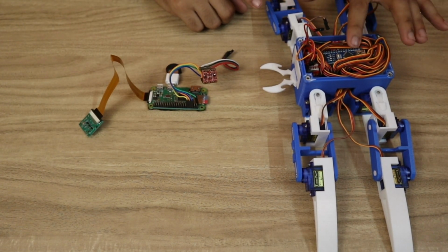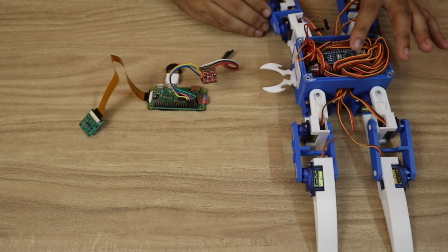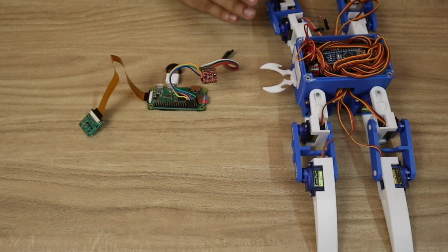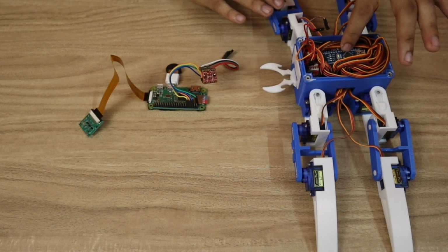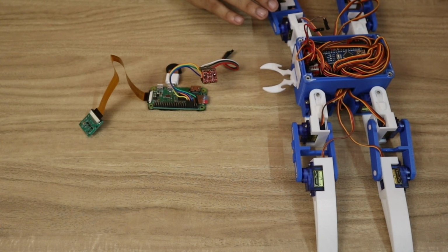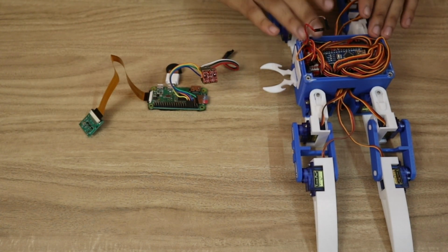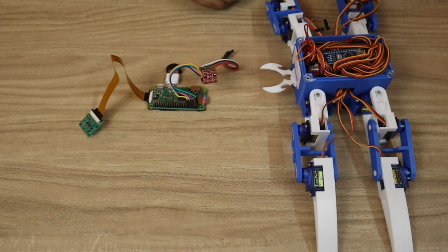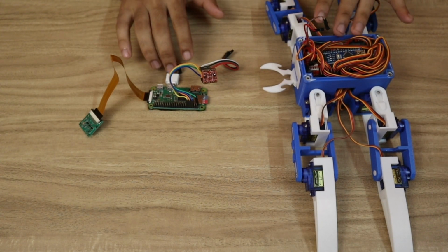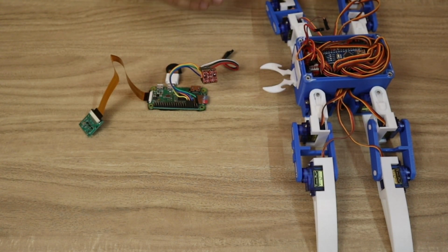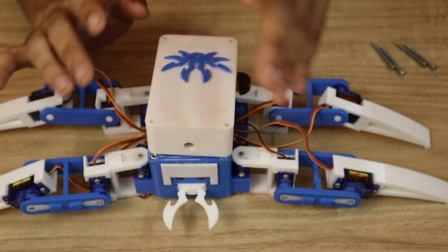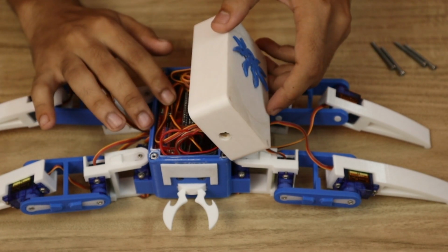Okay, and another thing is, make sure all the servos are working with the Arduino. How to check? I have already explained this in the last video. Also, I have given you a sample program using which you can check that. So please watch that video and check if all the servos are working with this Arduino or not. Okay, so after you check that everything is working just fine, your spider is going forward, backward, left, right with this Arduino only, then you connect this Raspberry Pi with this, and then your hardware part will be done.